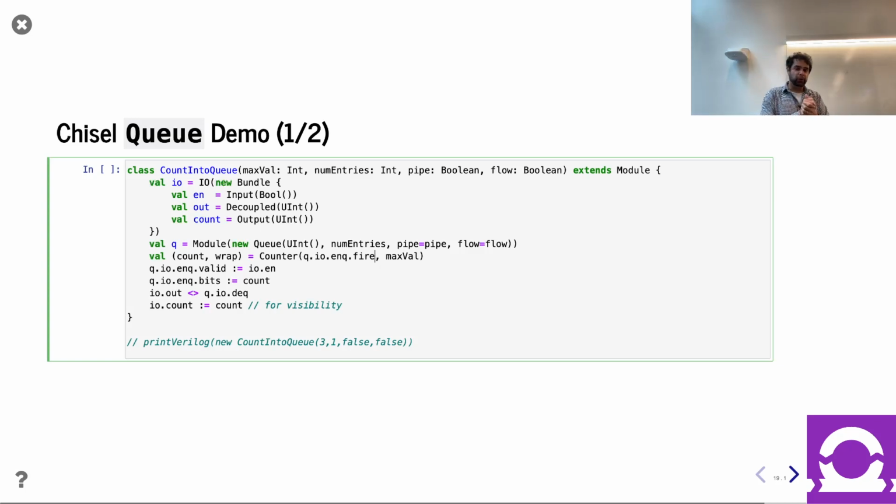Now, earlier in the lecture, a question about something like AXI was asked. So you can imagine if you have IP blocks on your SoC talking via a protocol like AXI. It's much more sophisticated than what we're talking about right now, but at a high level, that's a decoupled interface, right? If someone sends you an AXI command, you need to obey the AXI protocol, but you're not required to respond to them immediately. So AXI does give you the same capability of having a decoupled interaction. It's just a lot more complicated, with a lot more features. This is a very low level, bit-centric thing for perhaps smaller modules communicating rather than giant IP blocks.